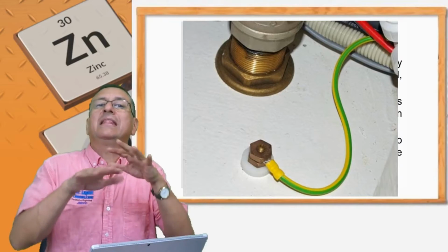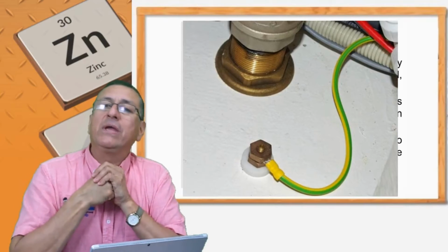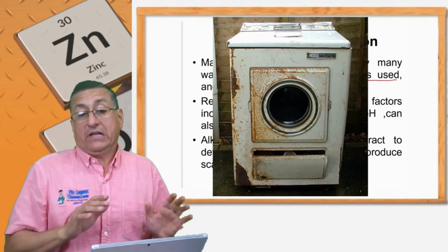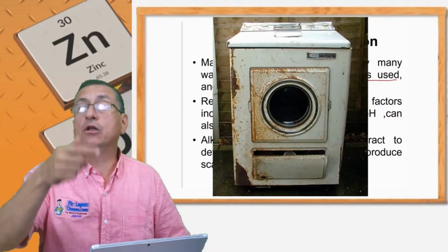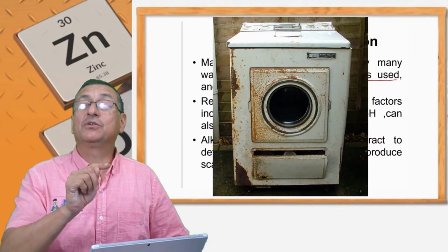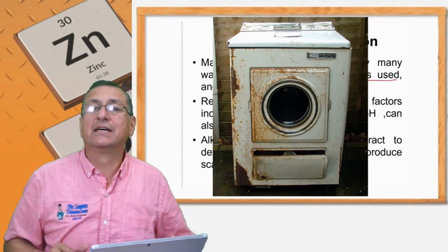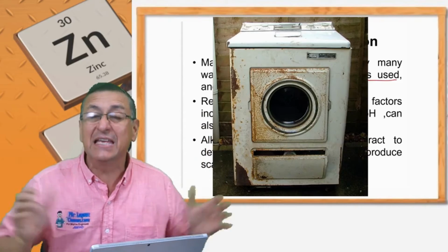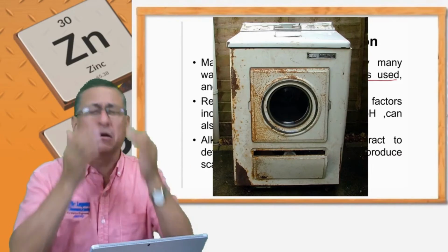And what happens when the energy is stored over there? What happens with that equipment, with the appliance? In the case of that equipment, for example, the skin is steel, and the screws are aluminum or copper or other alloy. Dissimilar metals together with energy in between both of them. Static electricity stored over there. This is the worst scenario. You have a marine environment with humidity, you have dissimilar metals together, and you have moisture around.